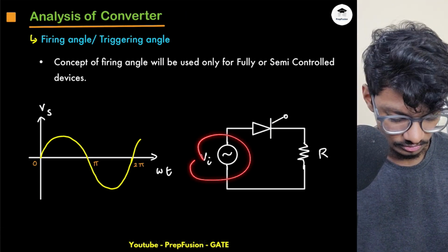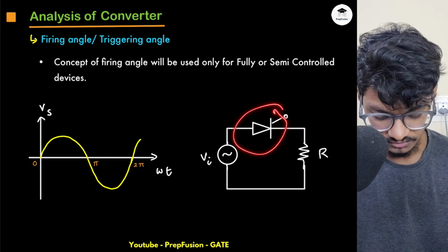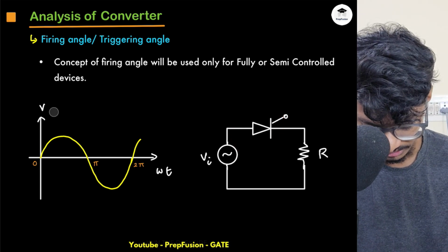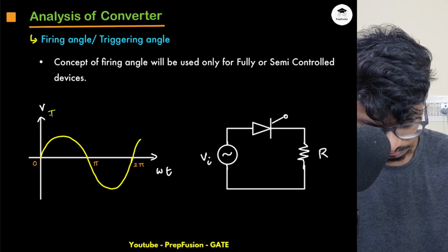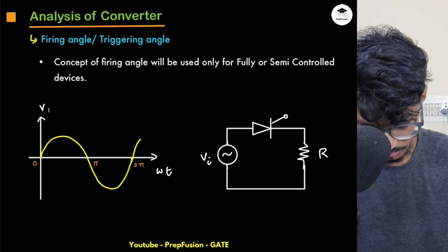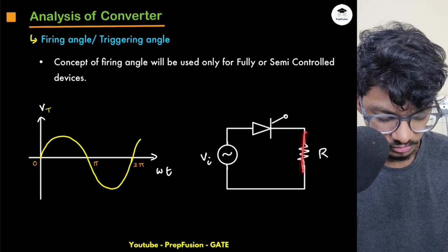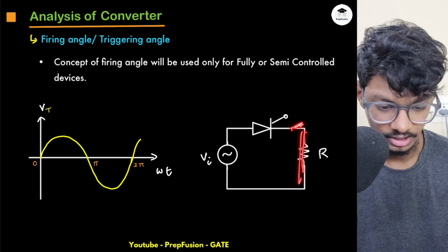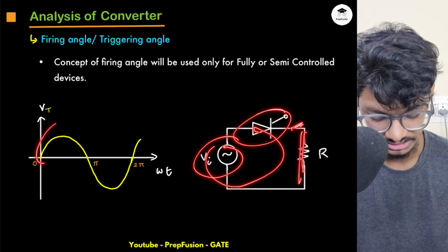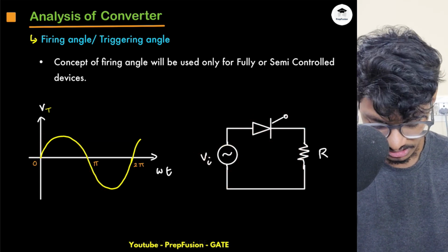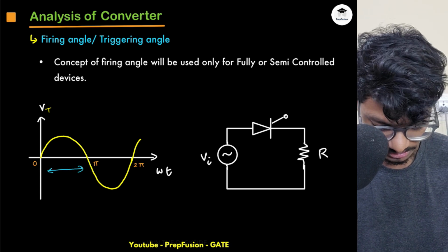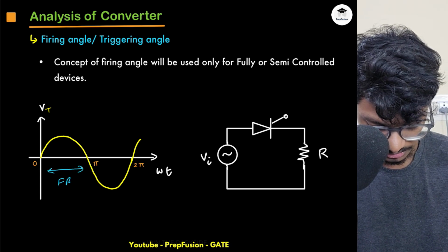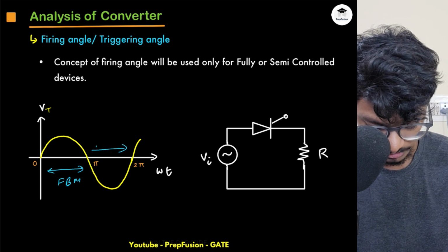I have already explained this in the visualization here as well. So here, what will be the voltage across VT? This is the VT, and VS is sinusoid. Here, current through it is 0. So this is like grounded, and this is the VS. So overall VS is coming across this thyristor, and this will be sinusoid. And only in this region, the forward blocking region, I will be able to control my thyristor turn on, and in this region I won't be able to control, right?